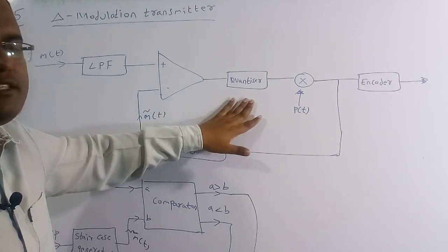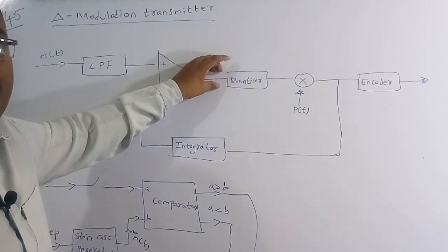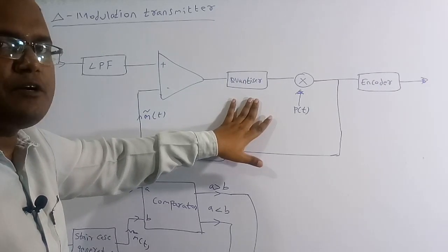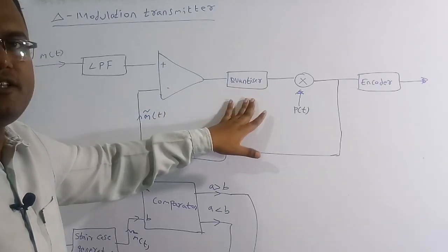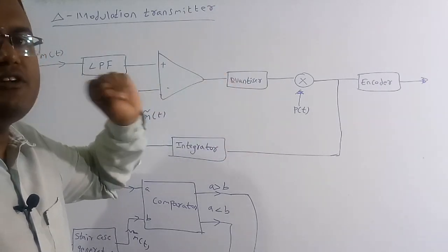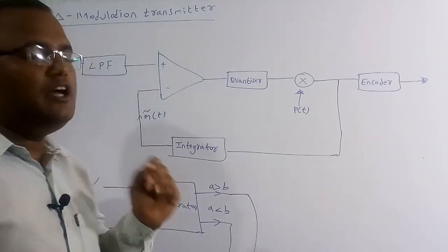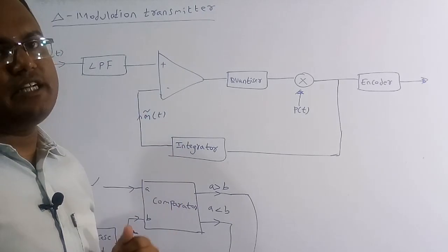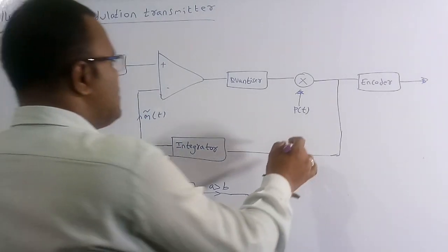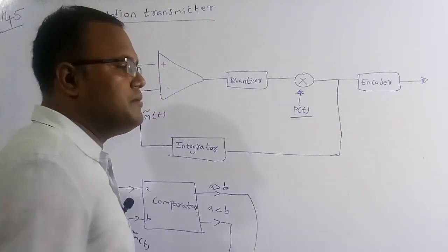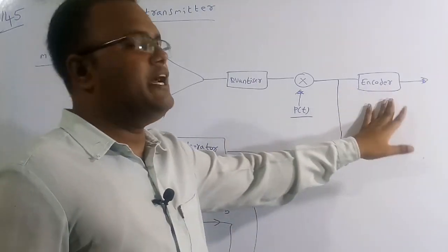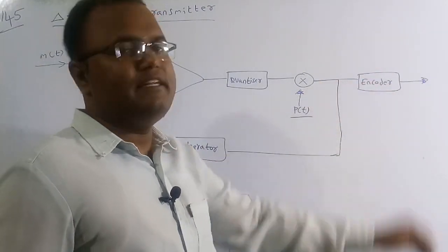So with the help of the quantizer, whatever output pulse we get, we are going to quantize to particular, finite levels. So with the help of standard levels, we are going to represent any of the infinite number of peak levels; we quantize to standard peak levels. Then again we modulate with respect to the pulse train, and encode this signal into a digital value.